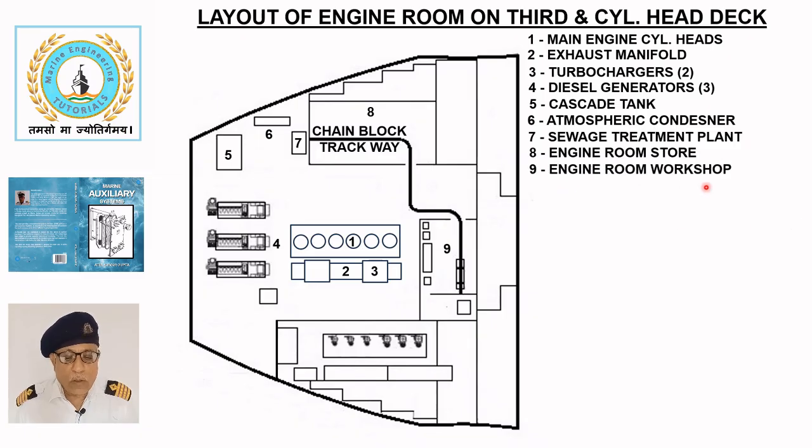Engine room workshop. The engine room workshop 9 is equipped with a workbench, a universal machine, a pedestal grinder, arc welding, gas welding, and cutting equipment. The fuel injector test bench is protected from heat sources by a separating wall.